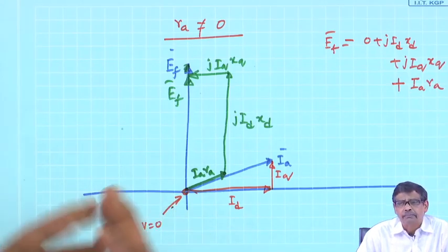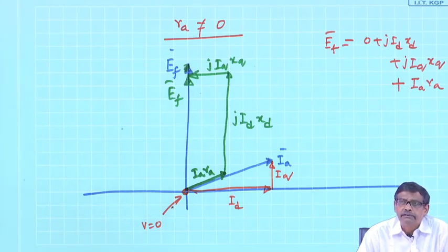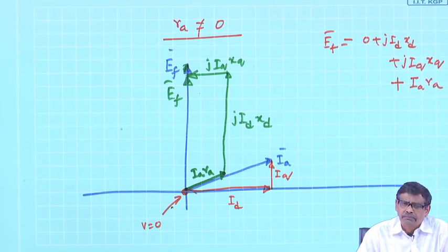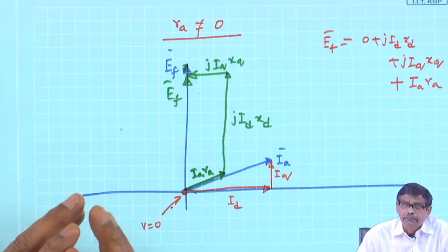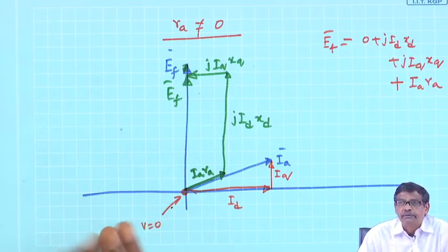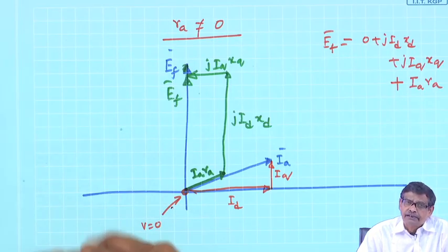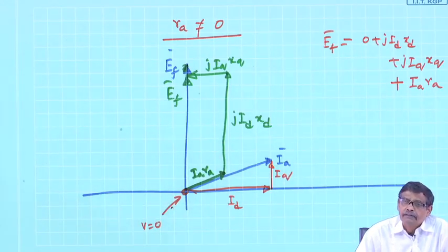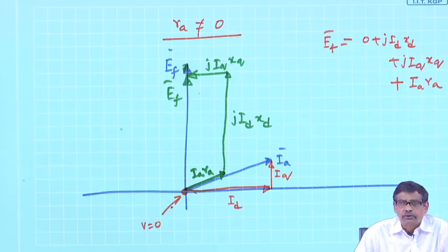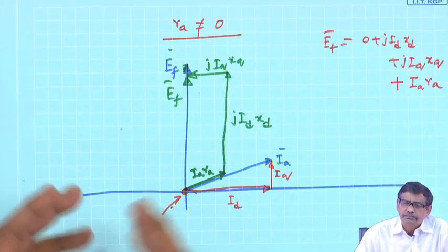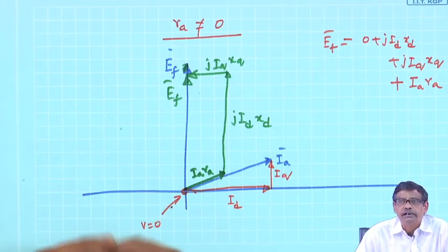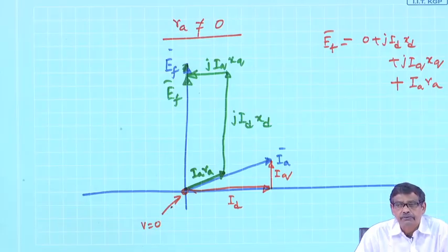So I discussed armature windings, not in too much detail, but very basic armature winding: 60° phase spread, 120° phase spread, 3 phase distributed winding. In the induction machine, in the stator and rotor, this type of 3 phase winding is used, and if such windings are used in the rotor of a 3 phase induction motor, it is classified as a slip ring induction motor.